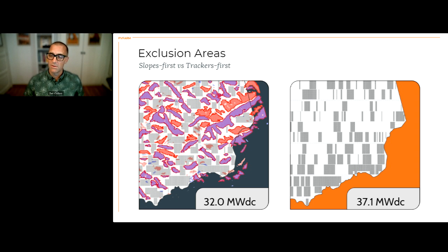The tracker is a component of it, but the tracker is the component because the piles are connected to the tracker. And when we're looking at these, as I said earlier, just because the slope is high doesn't mean it's unusable, because it really depends on how the piles are landing, where they are on the site, and what sort of variance you're allowing across those slopes. And you can't really know that answer without getting into that next level of detail. That's the piles, that's the lengths, that's even the types of piles if you want to go to that depth.